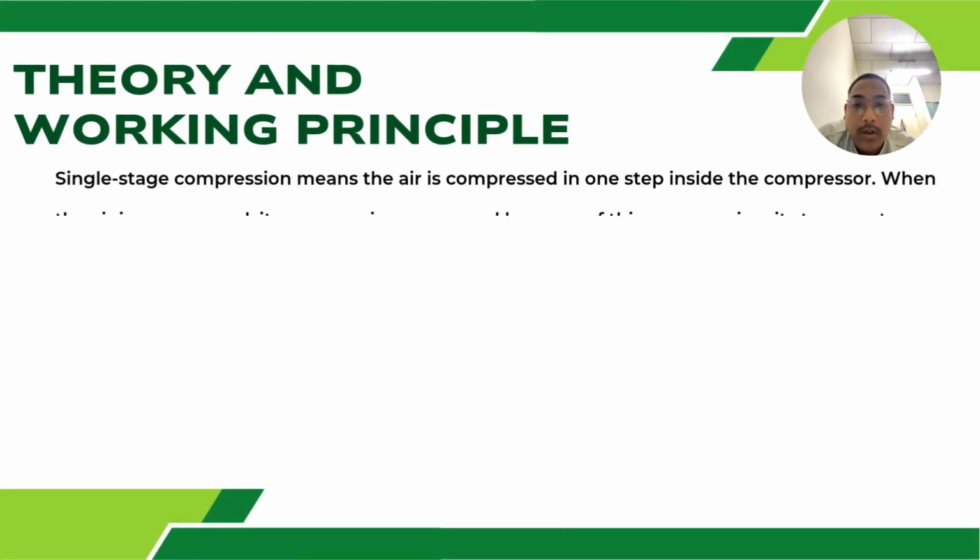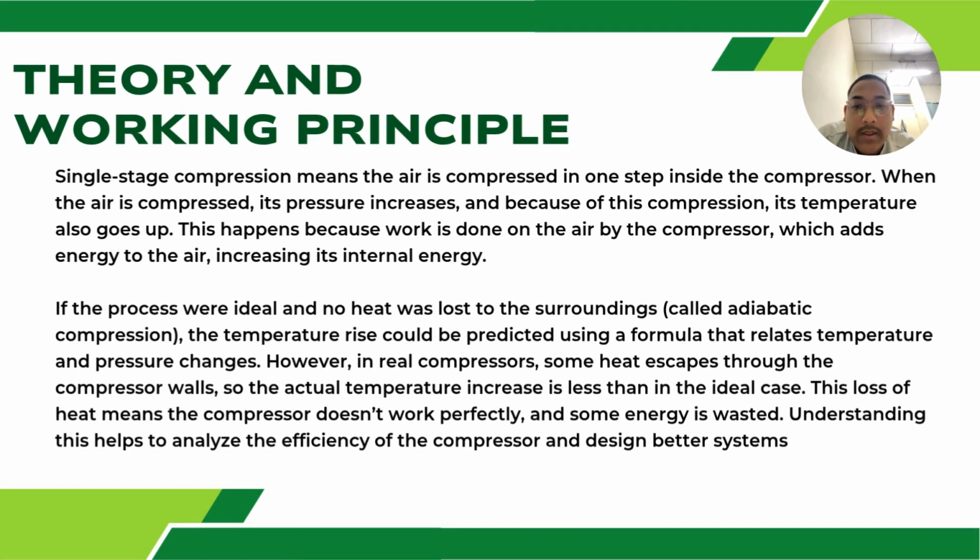Okay, for theory and working principle. A single stage compression means the air is compressed in one step inside the compressor. When the air is compressed, its pressure increases, and because of this compression, its temperature also goes up. This happens because work is done on the air by the compressor, which adds energy to the air, increasing its internal energy. If the process were ideal and no heat was lost to surroundings, called adiabatic compression, the temperature rise could be predicted using a formula that relates temperature and pressure changes.